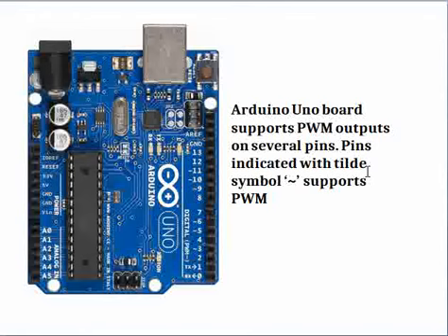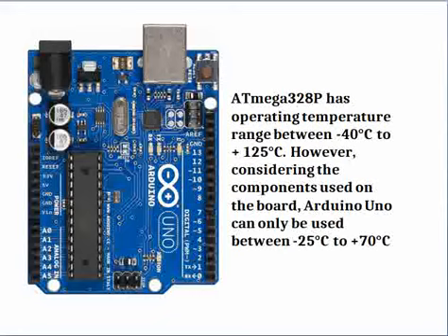So you need an application, in any situation, that consumes as little power as possible. In that case, you can do PWM controlled LED glowing, where you see that the LED is continuously glowing, but ultimately in the background it's a PWM control. That means you are saving some power instead of having it continuously on. Very, very important. We'll see about that in future videos.